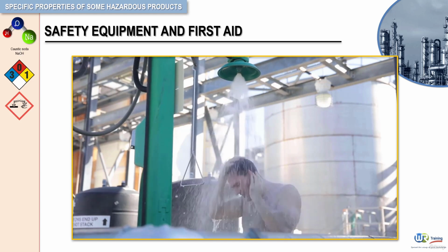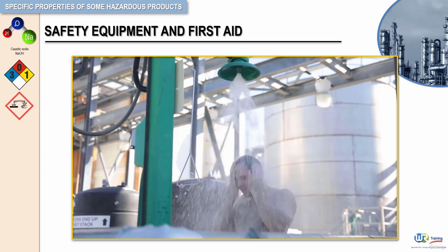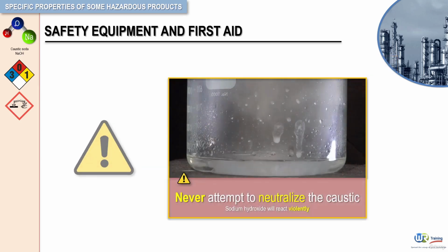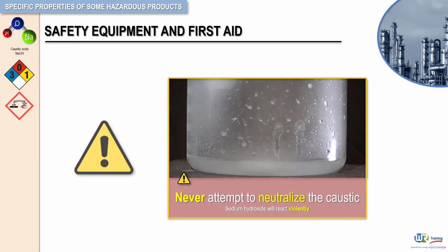When personnel have been exposed to caustic solutions, additional medical treatment may be necessary. Never attempt to neutralize the caustic. Neutralization is an exothermic reaction that produces heat and can cause thermal burns as well as chemical burns. In addition, do not apply oils to burns without specific instructions from medical personnel. When necessary, the victim should be moved to a medical facility immediately following prescribed washing.